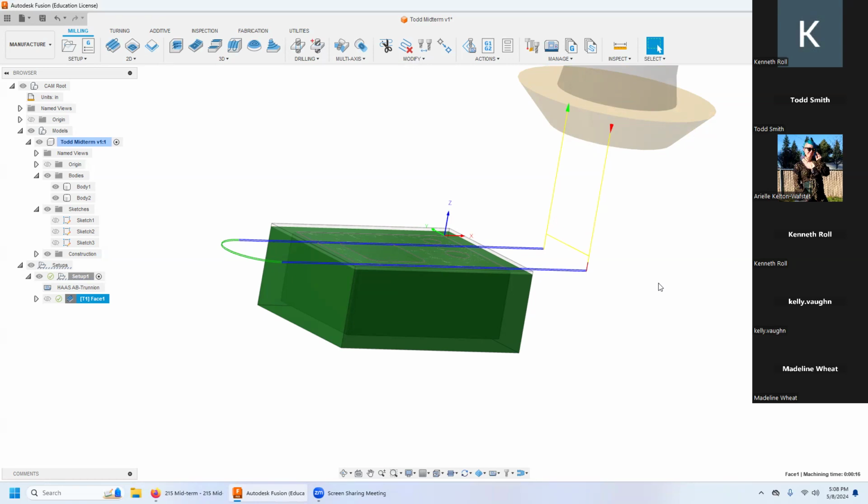There are times when it's appropriate when you are using a ball end mill, for example, and you're stitching a sloped shape. Sometimes it's nice to have a vertical lead in, just in case you don't have room for a horizontal lead in. I have at times used it, but for the most part, it's going to cause undue anxiety to your setup person, or an operator. How's that? Okay, thank you.